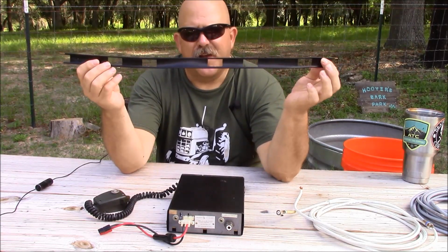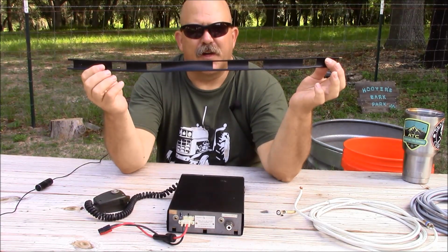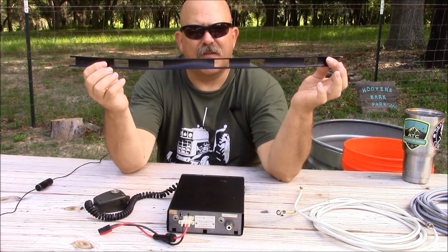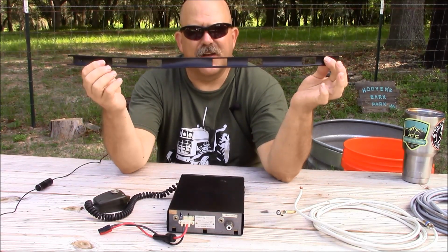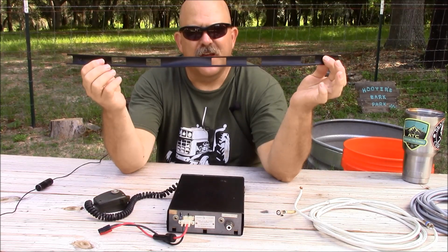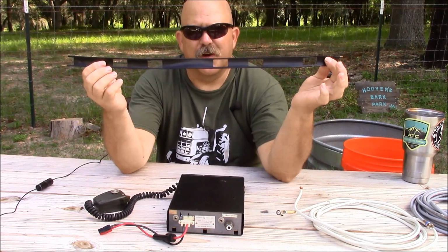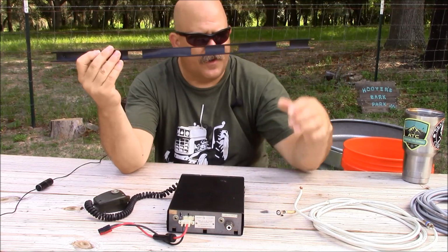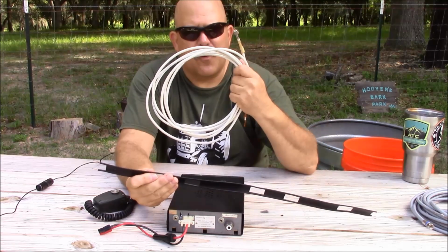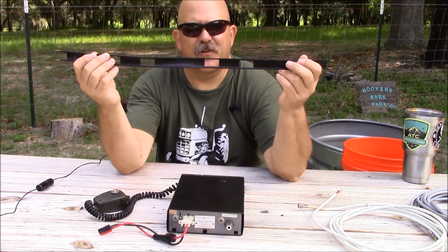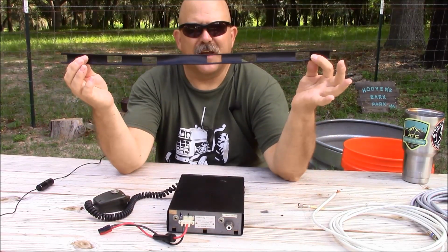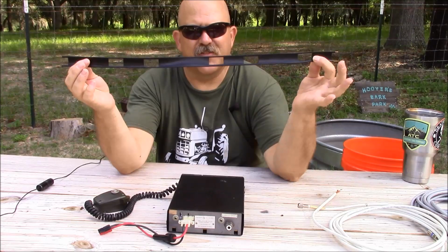But when it comes to making an emergency feed line that we're going to have to press into service, we're going to end up dealing with making a line as a parallel feeder because that is what we have available to us. It's going to be easy to construct. Again, trying to construct a coax cable out of the materials we may be able to come across is going to be extremely difficult, whereas making a balanced feeder is going to be much easier.